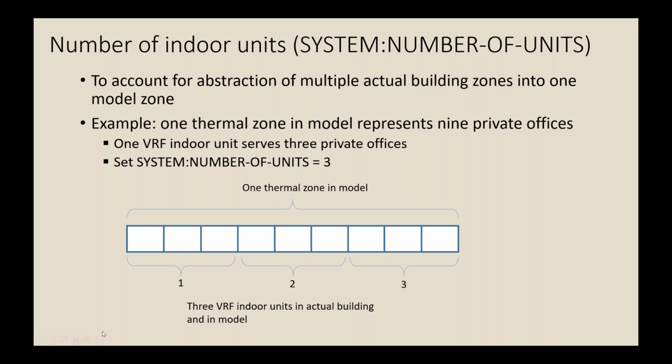And that's the whole purpose of this functionality, to allow you to keep your model simpler overall, but still give you accurate piping energy calculations. So this basically just splits the piping into three parallel segments instead of one large pipe, and so it gives more accurate results for the piping. Okay, thank you. Yep.